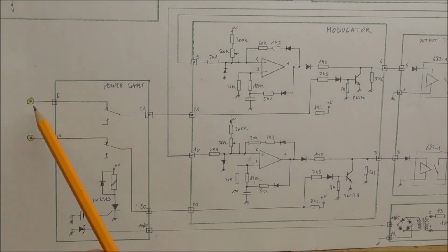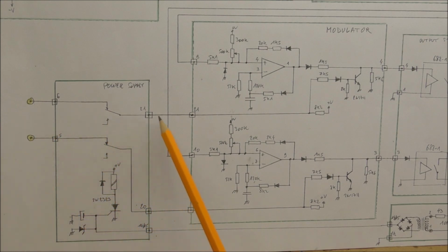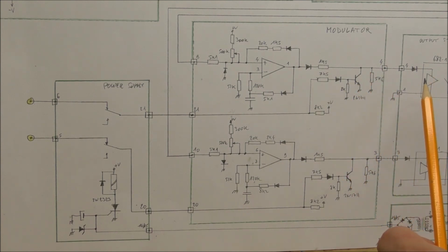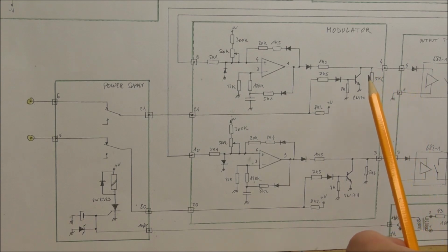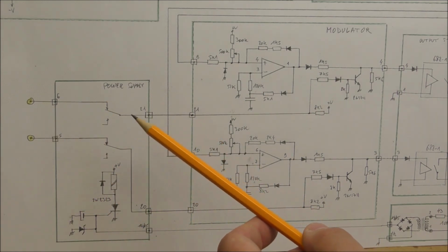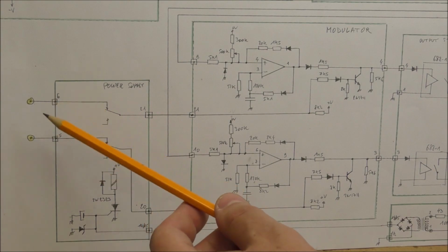We can see that we have two signals which are available on the rear connector. The signals are connected to the bases of these two transistors. These transistors permit to shut down the output stage, so it is possible to deactivate the heater or the cooler using an external signal here. So I don't know exactly the purpose of this thing. When there is an overcurrent, these two inputs are disconnected.